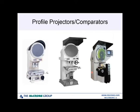Two types of measuring instruments that we are going to concentrate on are profile projectors and toolmakers microscopes, or measuring microscopes. These are examples of profile projectors, or otherwise known as comparators. Some people call them shadowgraphs. You can get up to 500x magnification. They may have 1, 2, or 3 objectives. They usually have a measuring stage of some sort, and they will have a screen onto which the image of the specimen of the part is displayed, as you see here on this instrument.